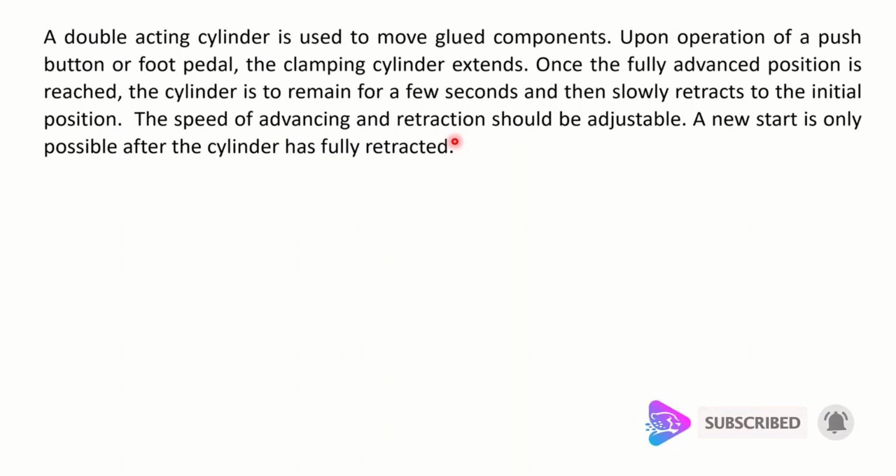And from there, after that directional control valve, we should have a twin pressure valve, right? And as you know, a twin pressure valve has two inlets. One of them is going to be in the actuation mode, because we're assuming the system is fully retracted. The directional control valve, which is linked to that position, is actuated and shifted, right? One condition is true, therefore the system is ready for the new cycle.